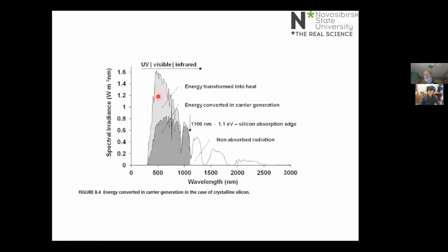And the advantage of those, what are called PV thermal systems, PVT systems, is that if you take heat away from the module, you lower the cell temperature. And as we'll see, lowering the cell temperature improves the efficiency of the PV system.